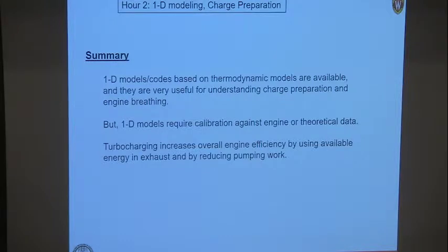Okay, so what I've tried to do in this section of the presentation is to discuss how you can use these 1D models to set up an engine system. And this is widely used in the industry. Every OEM has GT Power and Ricardo Wave experts, AVL Boost experts, who design the entire layout of the intake system, the turbochargers, the compressors. And everything is done without considering the combustion chamber.